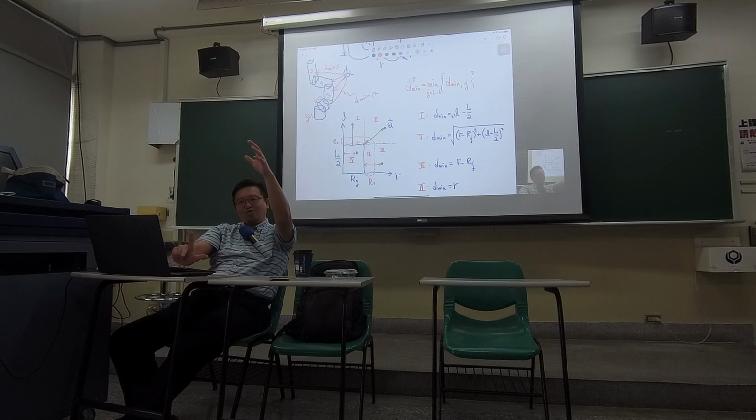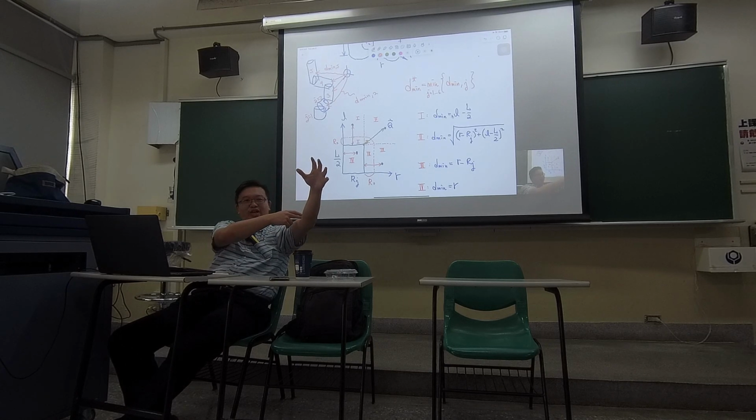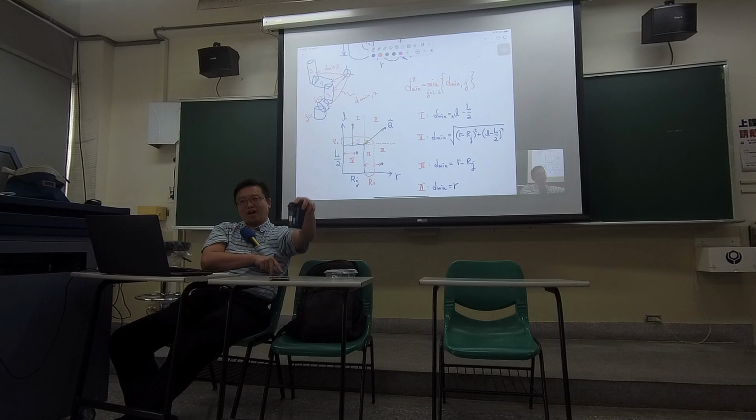So you need to know how to transform from the world coordinate to this body fixed frame by forward kinematics, because you know at this configuration, you know all the joint angles, you know the geometry, you should be able to find out what is the body fixed frame on the jth body at the ith configuration.